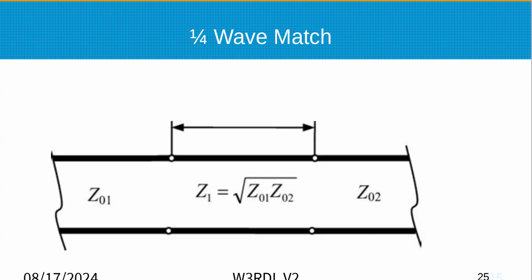Okay, thank you. Because when it's matched, the antenna hasn't changed, it's whatever it was. What you're seeing should be purely resistive. In the real world, it won't be exactly, but in theory, it would be resistive if it was at resonance.